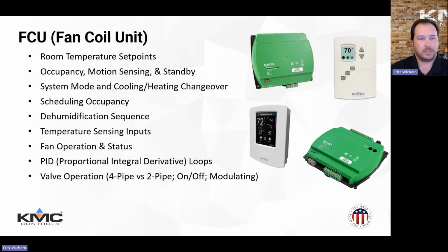Our dehumidification sequence is available in some of these profiles, depending on whether you have the associated STE 9000, I think it's the 9021 net sensor, that has the internal humidity sensor built into it. The dehumidification function regulates the humidity levels in the space, using set points and differential values to activate cooling and heating valves to maintain comfort. A couple of notes there: the heating and cooling modes do need to be in automatic for that to function on its own. Also, it's not available in two-pipe applications.